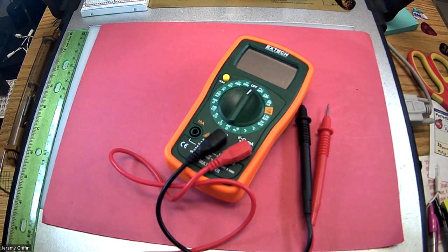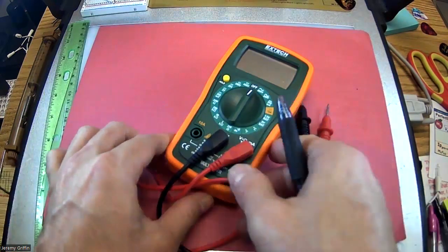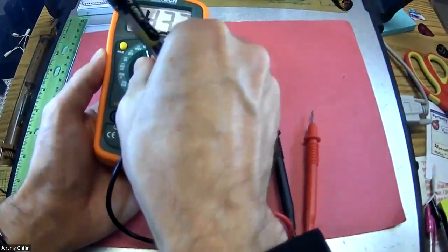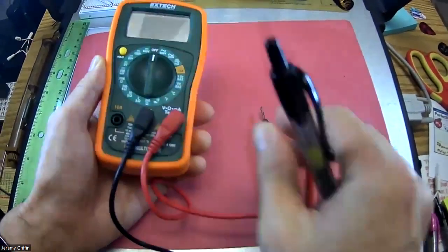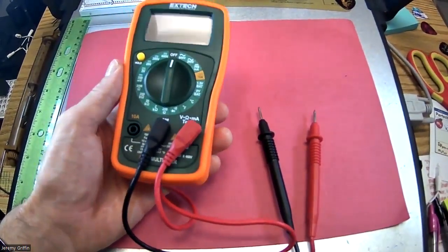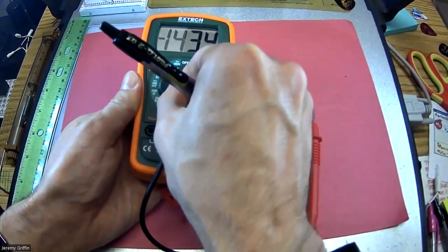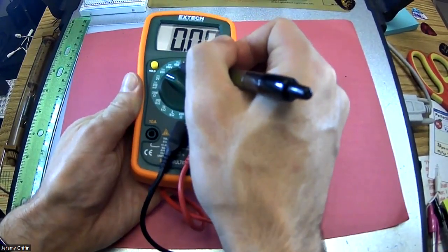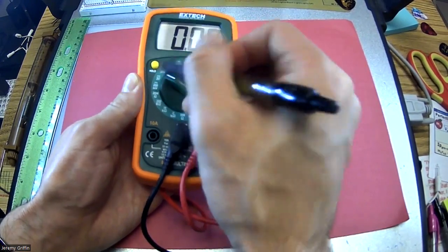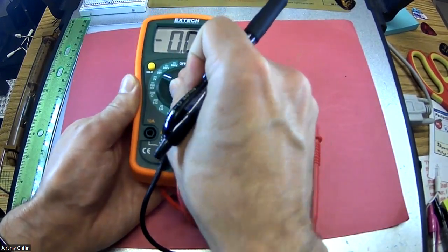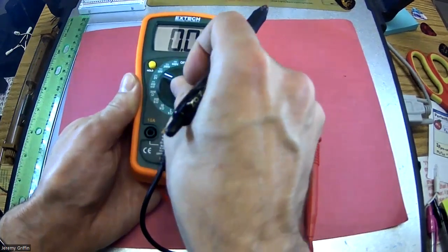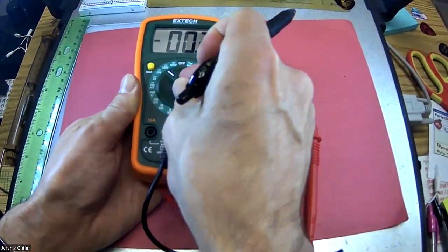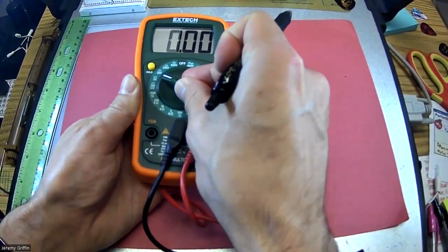So I got this multimeter. Now, multimeter means there's multiple things you can measure. And I got this toggle switch. There's all kinds of things I can possibly measure, right? Okay. So let me zoom in here. On this left side, I see something to do with voltage. I see like a bunch of V's. So it's like 600 volts, 200 volts, 20 volts, 2 volts. And as I switch the toggle switch, all that's changing on the screen is the decimals moving. So if I had hundreds of volts, I might want to use that one. If I had like tens of volts, maybe that one. If I had like single volts, maybe that one.